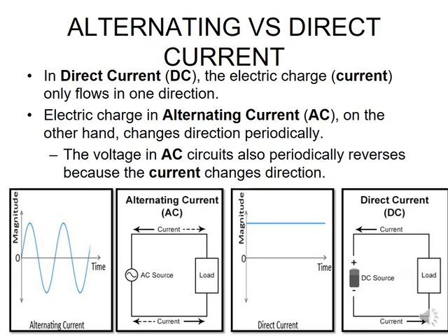So it basically means that you can have a scenario where, if one of your two lines from your source going towards your load were to have a problem and became open circuited or blew, whatever the problem might be, you could still get supply to your load by supplying it from the other side of that AC source. Whereas on your DC, if you lose that negative line, then that's it. You don't have supply going towards your load.